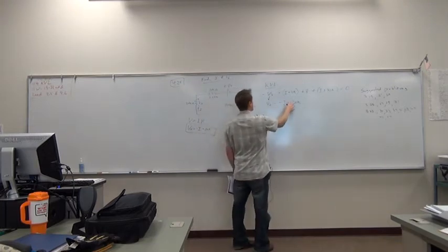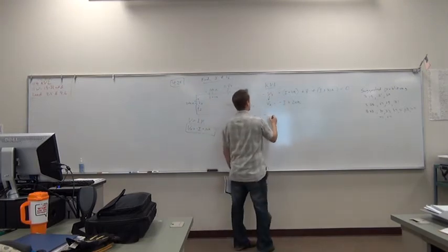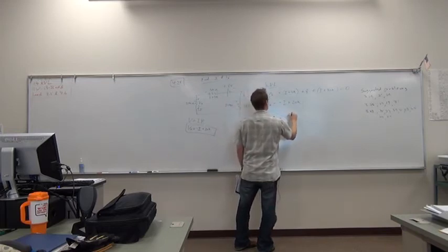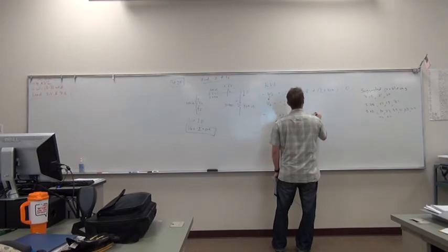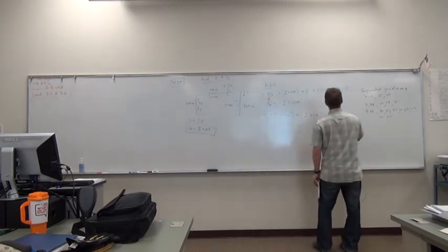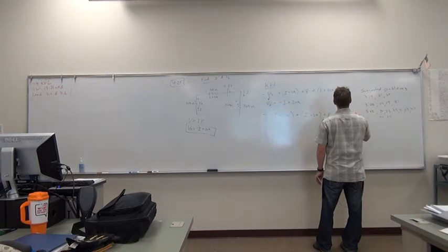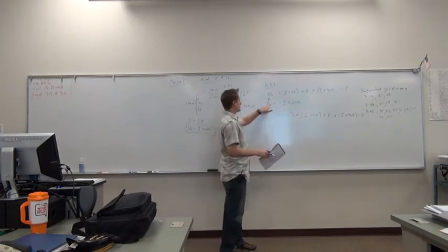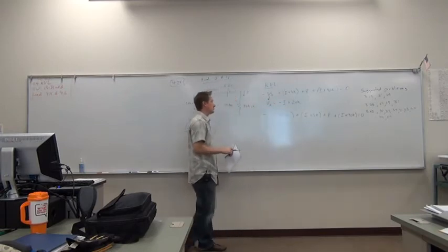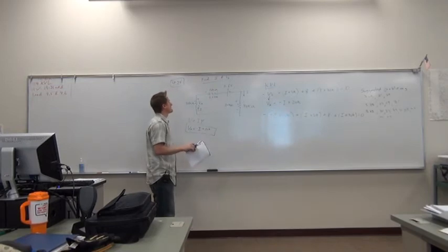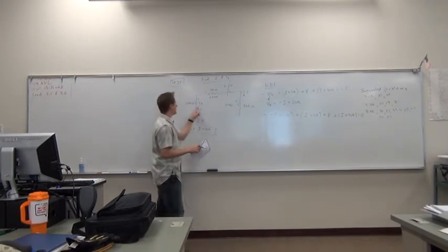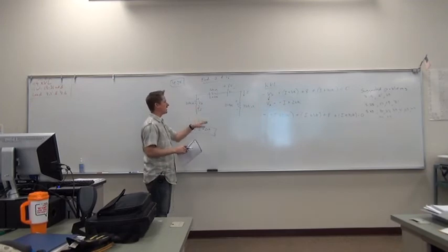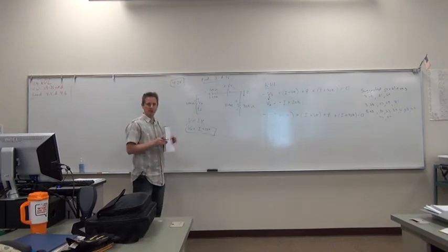Now we take this and we substitute in for that. We get minus I times 20K plus I times 10K plus 8 plus I times 40K equals 0. So really we have the same thing we had before. We just substitute the Vx for that part of the equation. The first minus came from the fact that we went through the source this way and we saw a minus. The second minus comes from the fact that whoever did this problem did not use the passive sign convention when they did it. So if you follow the rules, you'll always get the right answer.